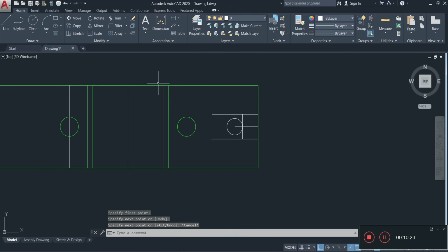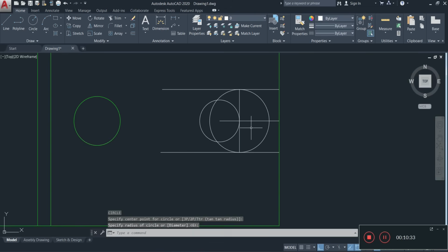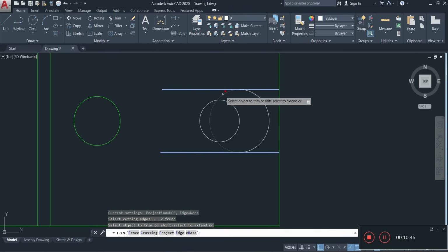So what I'm going to do, let's go ahead and draw that circle from here. You could use the arc tool if you like as well, and you're going to draw that one like that. Now this reference line on this one here, I'm going to go ahead and delete it. Then I'm going to do some more trim. I'm going to trim away this portion of the circle.